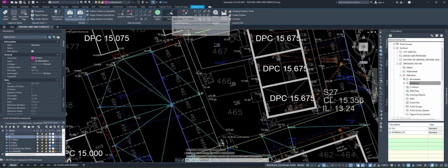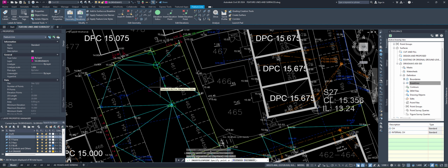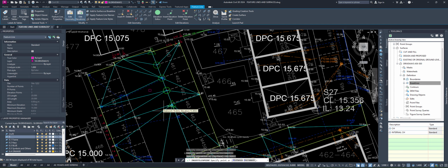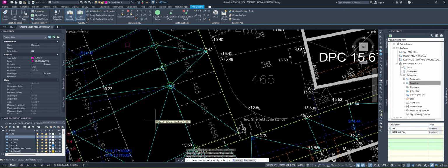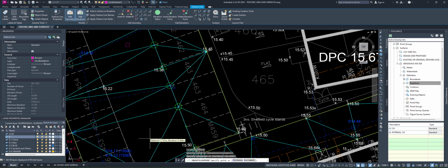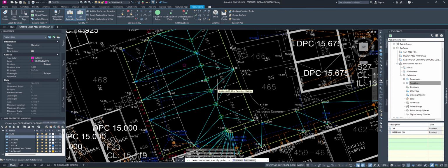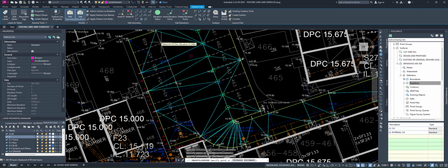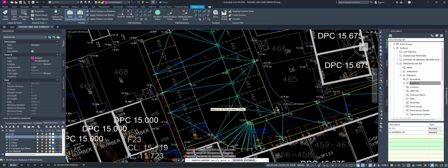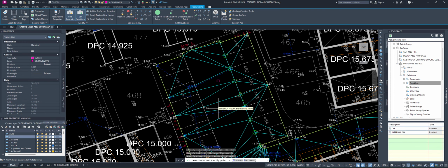Okay, I'm going to go to insert elevation point, and I can add a couple more elevation points. As soon as I start adding elevation points, you can see how I'm creating more and more triangles along. So a good surface is a surface with good triangles. Okay, as you can see, the triangulation is slightly better now. We can add another channel between this point, that point, and that point, and that is going to improve our triangulation even better. Let's actually do it.